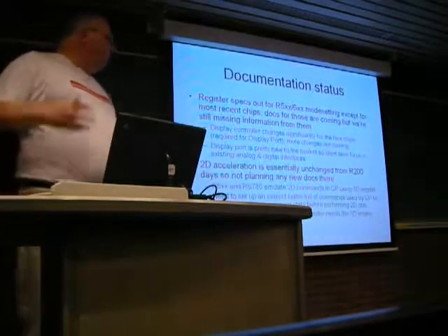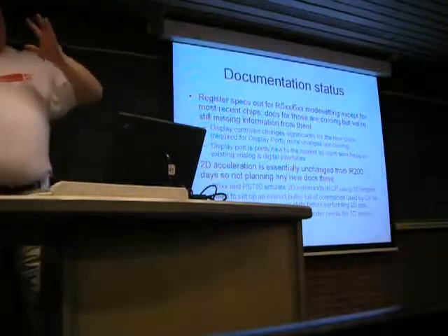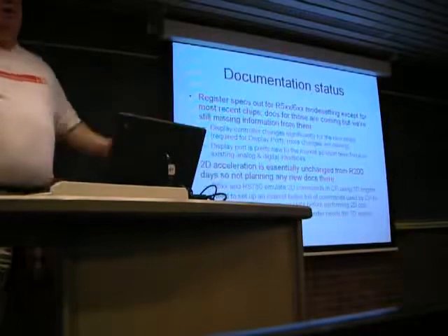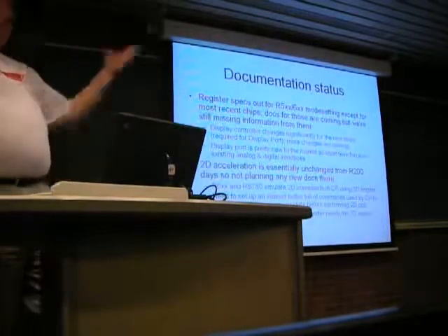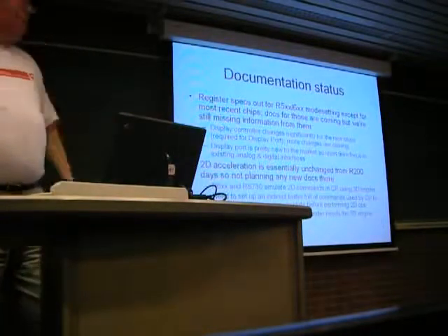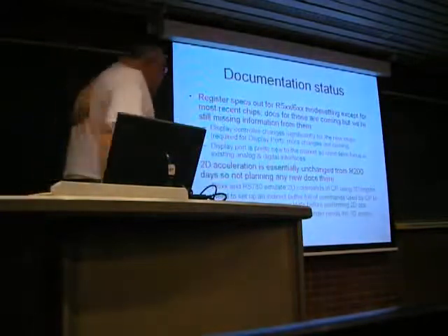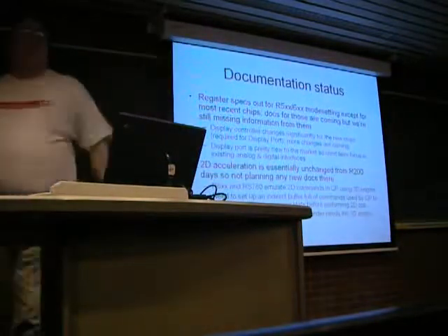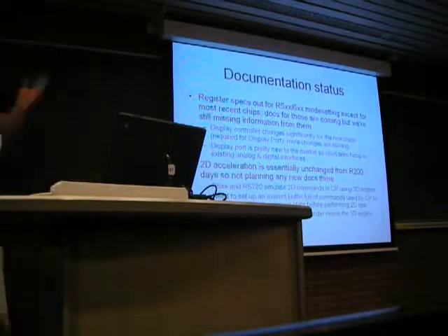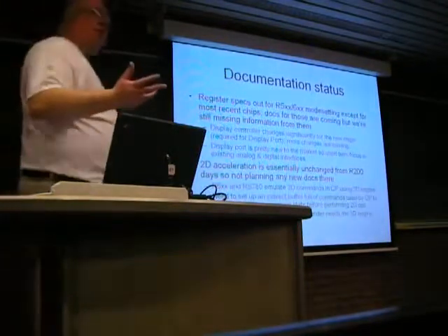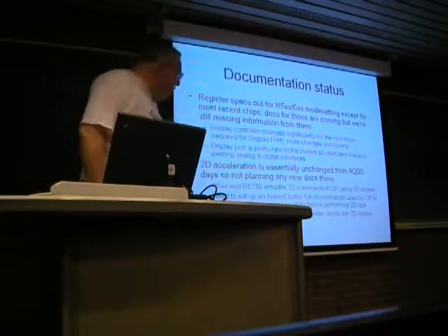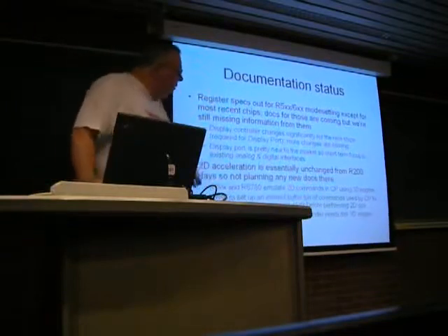What we're focusing on right now is just for the new chips, getting the existing display functionality, the analog, the DVI, HDMI, that kind of stuff, getting that working. And then we'll go back and do DisplayPort as a next step after that. So 2D acceleration, it really hasn't changed since the R200 days. The programming model, even the performance hasn't changed all that much. Memory buses are wider and stuff, but fundamentally it hasn't changed. So we're not planning on doing more documentation there.